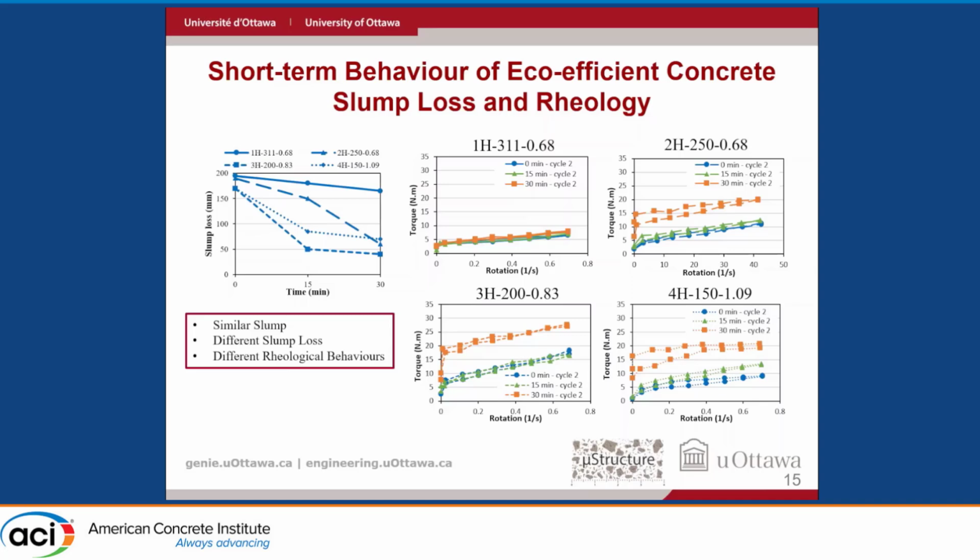So basically, the initial point here on the y-axis curve is the initial slump, if you want, that we also call yield stress. And the blue one is 0, just measured after batching, whereas we measure 15 minutes after and 30 minutes after. So again, as we can see, the slump loss is the same. So we keep going up on the y-axis for the initial torque. So we need a little bit more energy to enable flow, which correlates 100% with that.